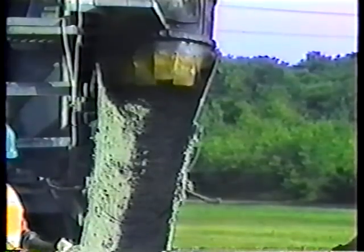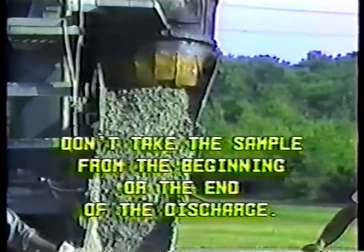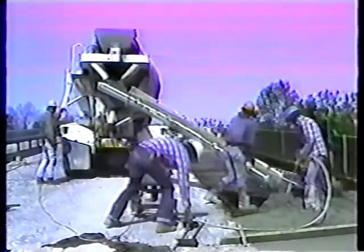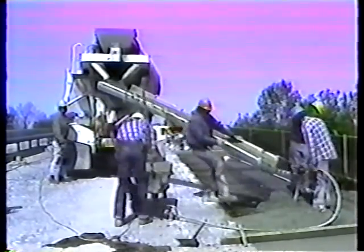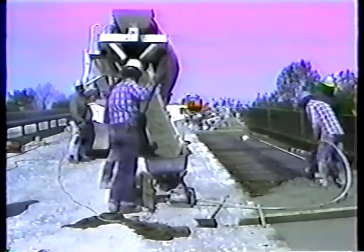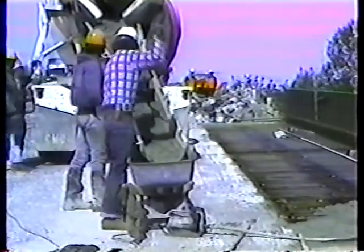The basic rule in sampling concrete is this: don't take the sample from the beginning or the end of the discharge. At least 3 separate samples have to be taken. I'd suggest taking them at about the 1/3, 1/2, and 2/3 points. Either catch the entire stream in a container or swing the chute over to the side. The important point is this: get the entire stream. Be sure to get enough concrete to run all of your tests without reusing any of it.